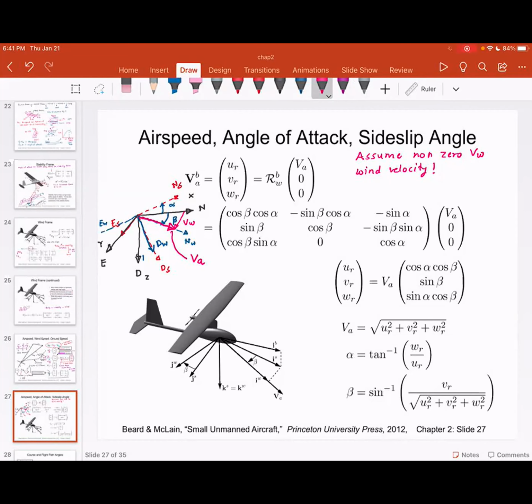So please understand. Now what I want to do is this VA, and this is super important. Please note this VA is expressed in the wind frame. That needs to be transferred back to body frame, and only then can the airspeed be expressed in the body frame.